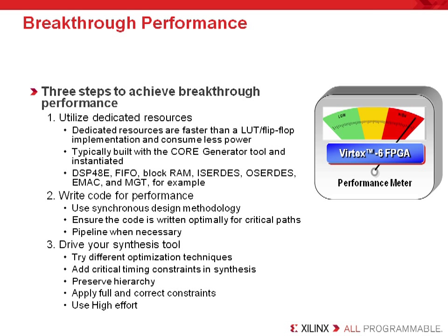Very often, customers choose a device that has some dedicated resources left over. So to get the most out of the FPGA, users have to very often pack the most into the FPGA, and in particular, those dedicated hardware resources they weren't using. Writing good HDL is of course important because it is used by synthesis tools to infer the most popular FPGA resources, that is, LUTs and registers.